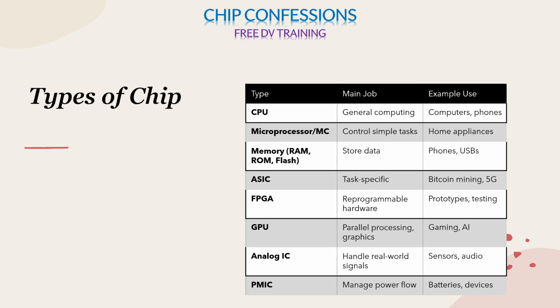What we will do here, whenever we are going for ASIC, it will cost more and it will take much of the time. Whenever you are doing a new design, you can't directly jump into something which is new, and you can't do trial and error here. So we just deploy that prototype or new design on FPGA, and we will check how it is working.